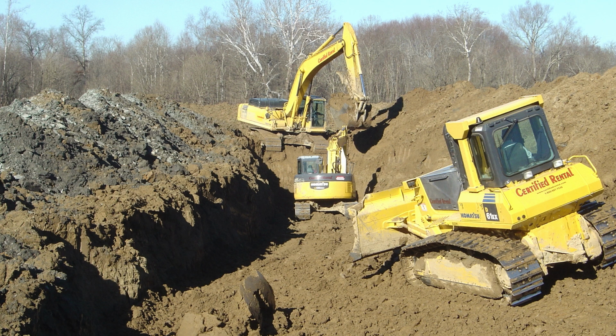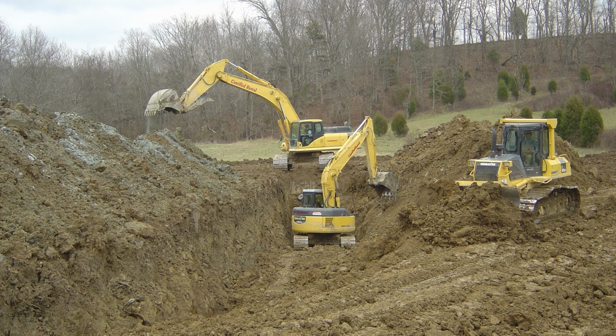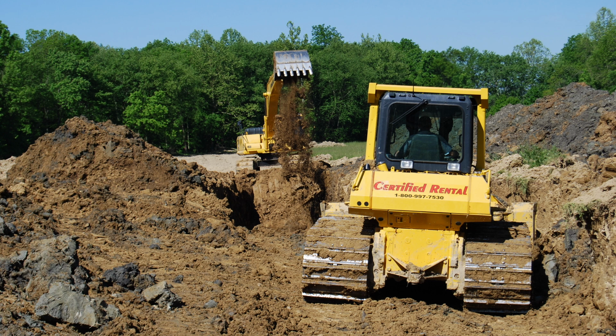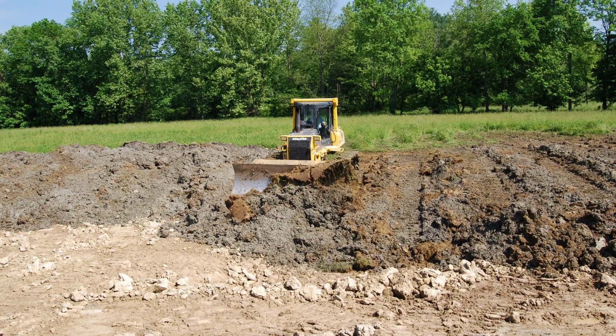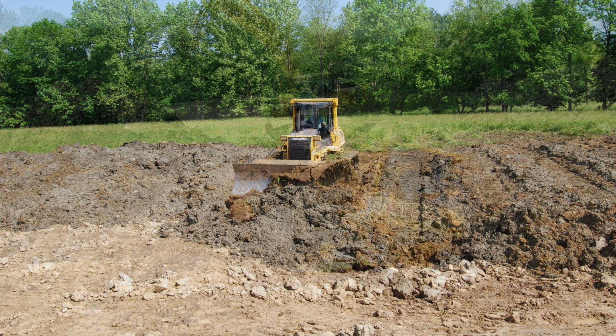It's of great importance to have at least one large excavator and one large dozer working together to build the groundwater dam. The excavator is used to dig the trench and to sort soil by texture. The dozer has many jobs, from removing and spreading the topsoil to supplying the excavator with clay and then spreading the gravel that's removed from digging the trench.